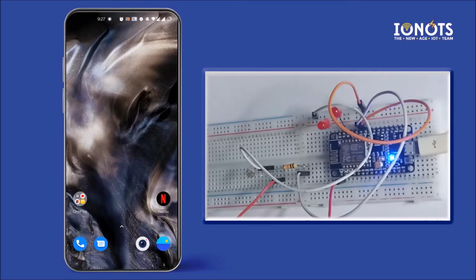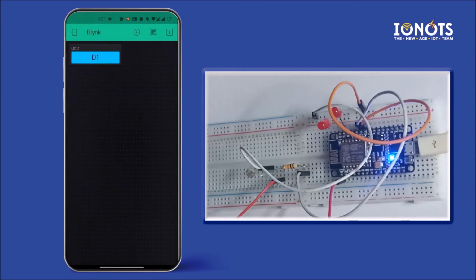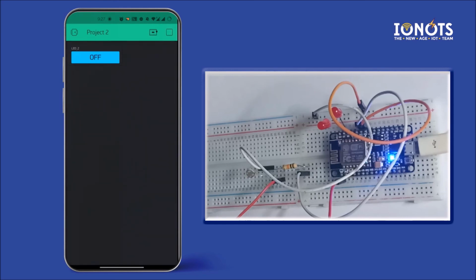For that, go to your mobile device where you connected the blink application. Now open the blink application. You will land on the GUI of the blink application that we created before. On the top right of the GUI, you will see a play button. Tap on it. This will connect the GUI to the NodeMCU. Now you will see a button. Its status is off now, and the LED status in the circuit is also off.